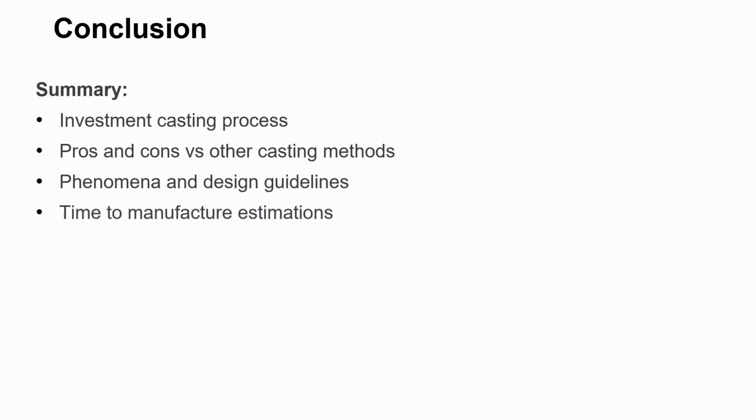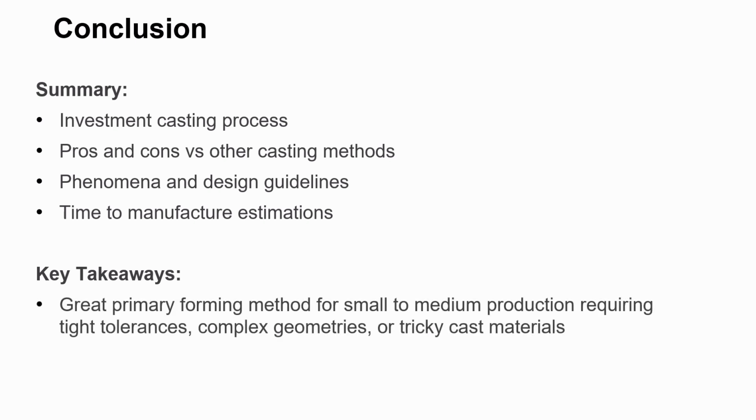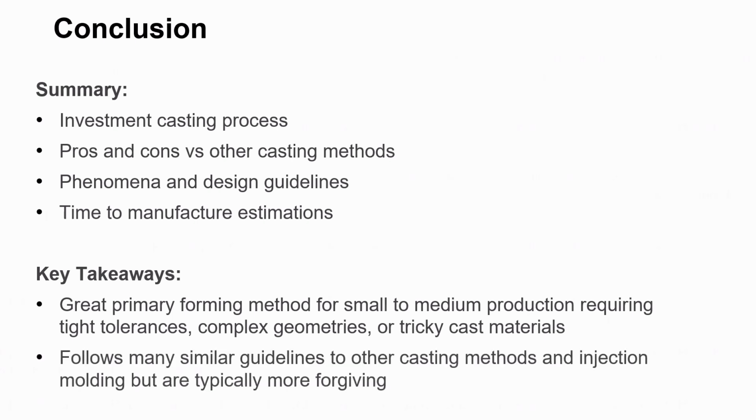And then finally, we laid a foundation for navigating how to estimate the process and cycle times required for investment casting. There are two key takeaways from this video that I'd hope would stick with you when assessing options for manufacturing methods. The first would be that investment casting is a great manufacturing method for small to medium production of complex components. The second key takeaway would be that the design guidelines are relatively easy to remember if you have prior practice or knowledge with other casting or molding processes, and that investment casting will almost always be the most forgiving option for many DFM requirements.